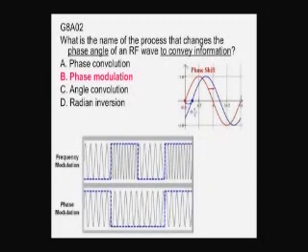The phase of a wave is not a change. It's a third characteristic of a wave. And really, it's a comparison between two waves. It's not a change in frequency. It's not a change in amplitude. It's a change in the position of the wave in time. This horizontal line represents time. And so the blue wave here is phase shifted just a little bit later than the red wave. It's essentially the same wave, but it's been phase shifted just a bit later.